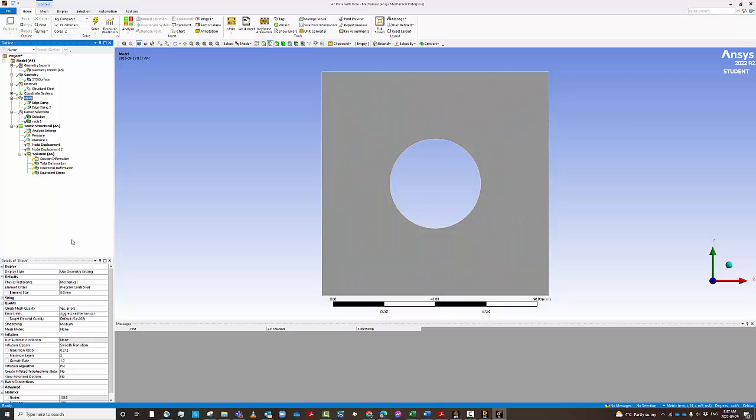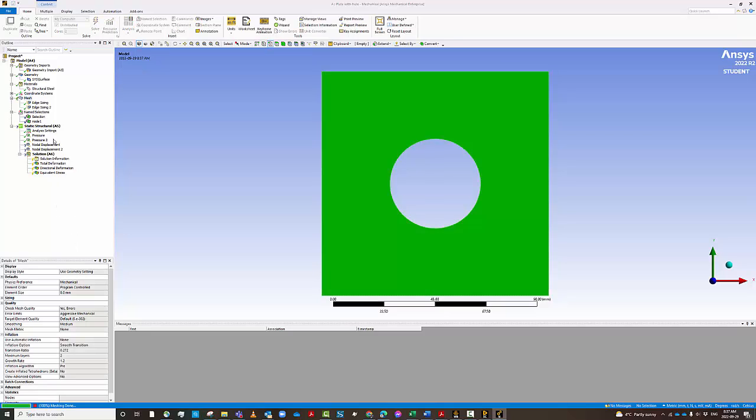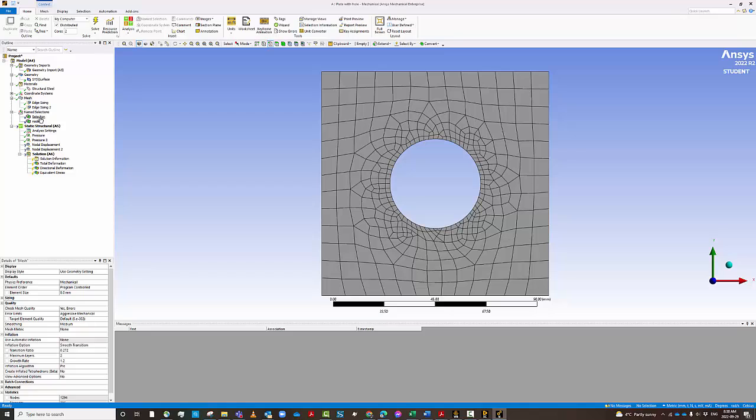update. And then as you update, of course, here the selections are going to be different because numbering of the nodes are different. We have more nodes now. So let me go to mesh quickly and let's see what we have. Now we have 396 elements and 1294 nodes. Before it was 11 something, right?